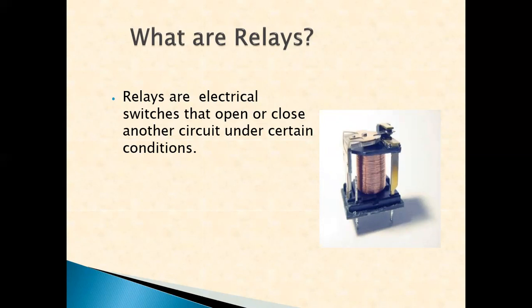The current and voltage are sensed by CT and PT, and from this, the abnormal condition is detected by the relay. The relay then operates, and depending upon the type of fault, it trips the circuit breaker or initiates an alarm or indication of fault. The job of making out differences between normal condition and abnormal operating condition is difficult. Example.